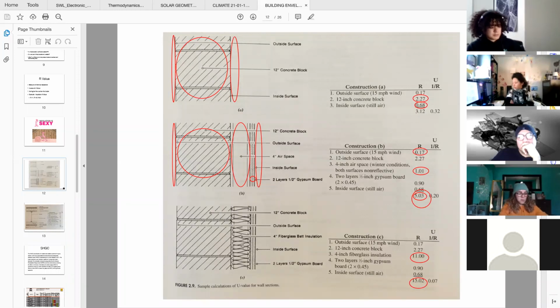Remember, I was talking about insulation last week. Smaller pockets of air to a large surface volume is what creates that resistance factor, because the heat is getting caught between all those little tiny surfaces around the bubbles of air that are hitting the fiberglass strand insulation. Okay, so these are 3 different wall examples.